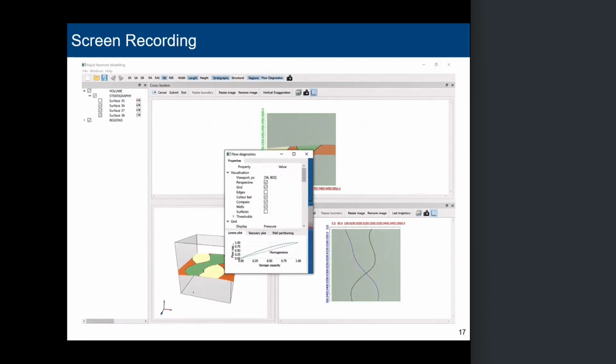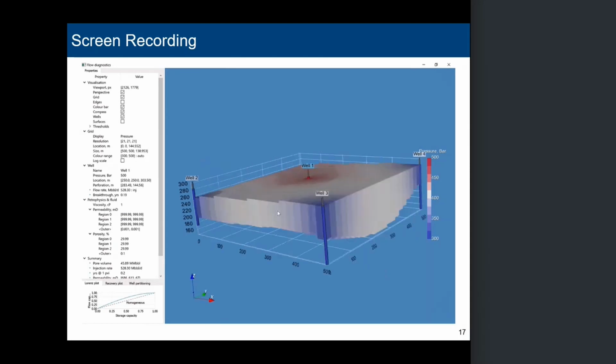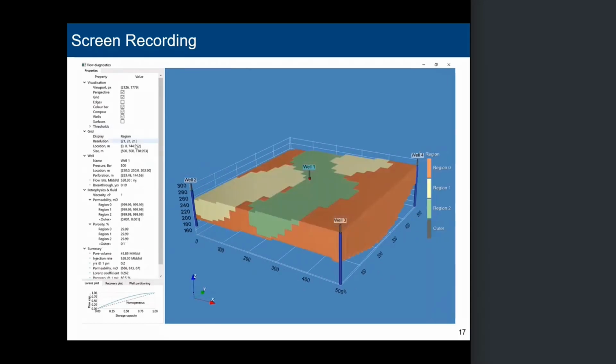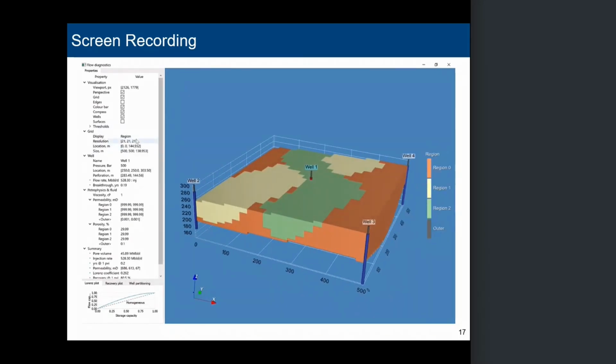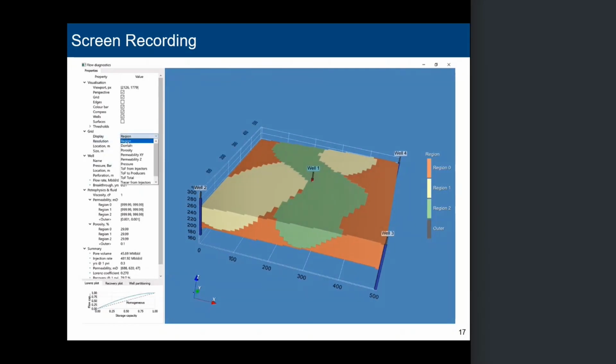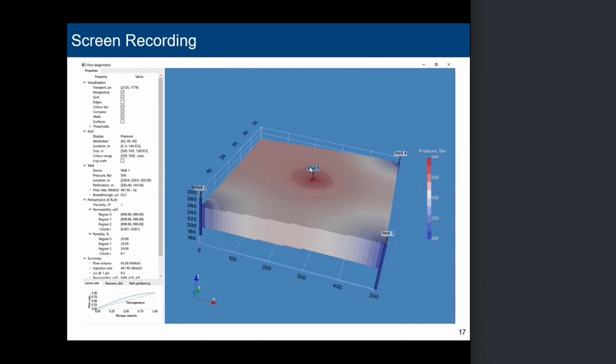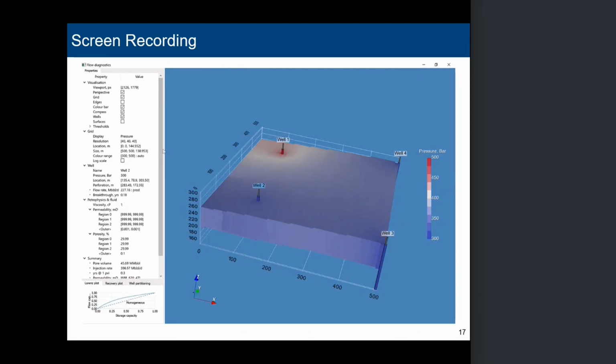We're now going to see that on the grid where we're making the calculation. Here we've got a coarse resolution. We just type in the resolution so it's higher. That's the higher resolution model. We've got an injector well in red and 3 producer wells. We're moving them around again in real time. The pressure field is changing in real time as we're doing that. So the calculations are all on the fly.